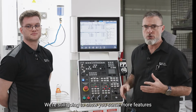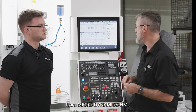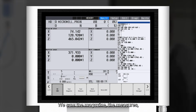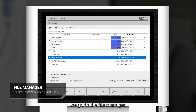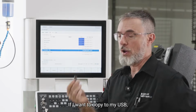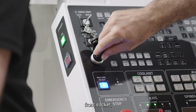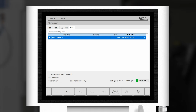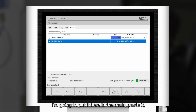We're still going to show you some more features from MICRO DYNAMICS HMI. Okay, here I have our menu. We saw the magazine, the measures. We go to the file manager. In the file manager, we have the memories, the hard drive, and this is our micro mill program that we just generated. If I want to copy to my USB front socket, I just choose it, copy it, go to the USB. Okay, I have a folder here. I'm going to put it here in the main, paste it, and I have it here. So now I can also transfer the files easily.